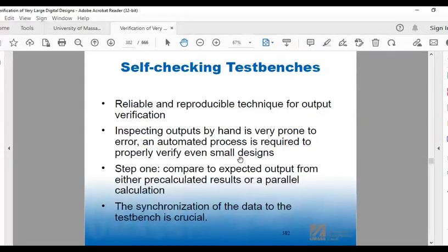We want to write a test bench that takes in a bunch of stimulus, which, by the way, is automatically generated, but I hope that's just implied by what we're talking about. Because there's really no manual method of putting in stimulus, so it's part of the test case. And then the output gets checked either against something that is formulaically related to what's coming out, so we know how to calculate the output and we compare it, or we have known data. Right? And in either case, we compare them, and the output becomes pass-fail. Right? Becomes this automated checker saying that the data passed or it failed, and this is what the mismatch was.